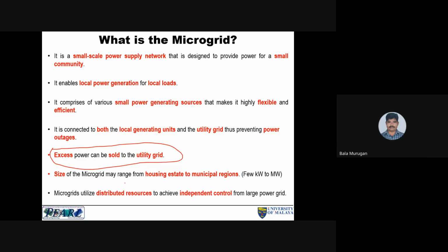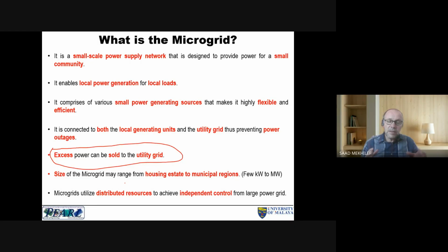Okay, sir. For home energy management, whether we can prefer a picogrid or microgrid? Yeah, within a house I can see it's a pico, a smaller size. If you want to call it a microgrid, there's no harm in calling it that, but microgrid is meant for kilowatt to megawatt levels, like I said just now. It doesn't matter what it is called. What matters is how the energy management between these sources and the loads works. You may have harmonized AC and DC, like we will see later.